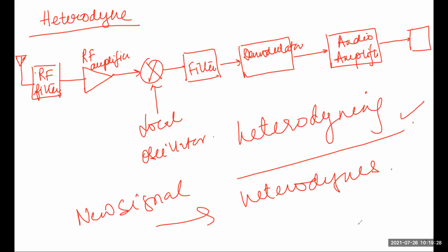So the heterodyne principle is that multiple frequencies applied to a non-linear device produce new frequencies that are sums and differences of the applied frequencies, and definitely their harmonics. That is the heterodyne. Homodyne is also a thing, but homodyne is not required here. So heterodyne comes from heterogeneous.